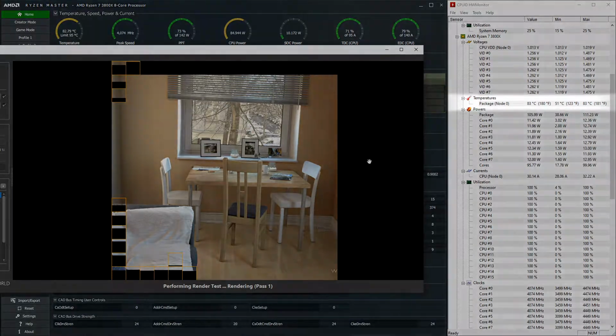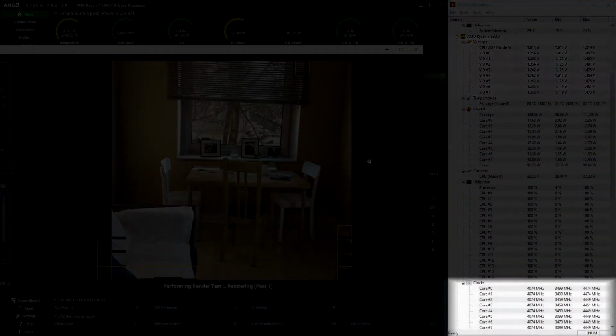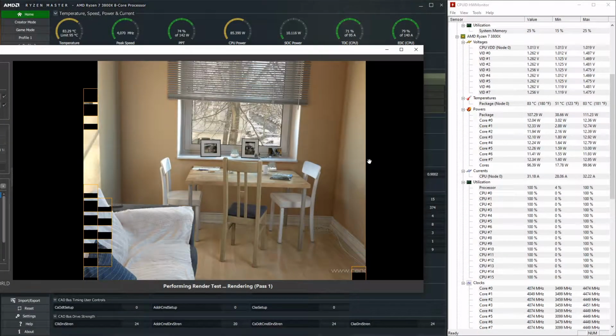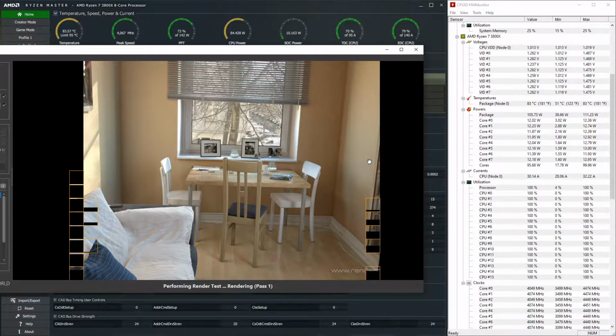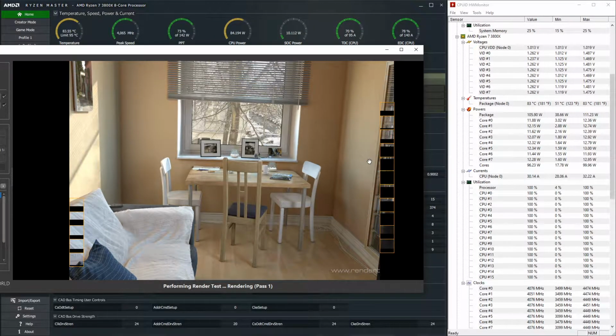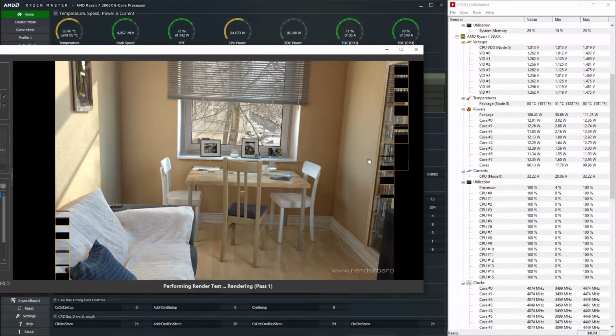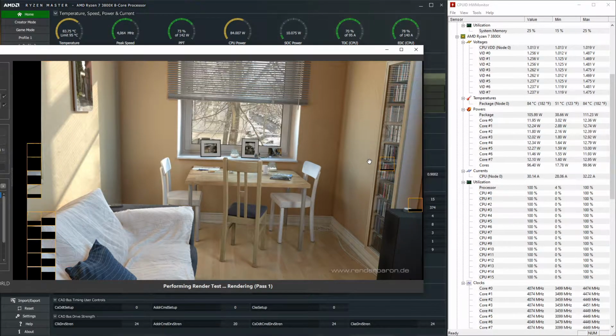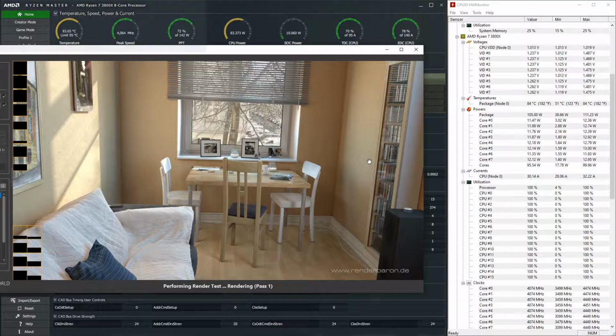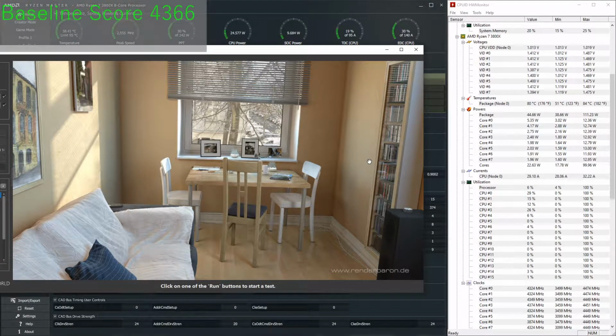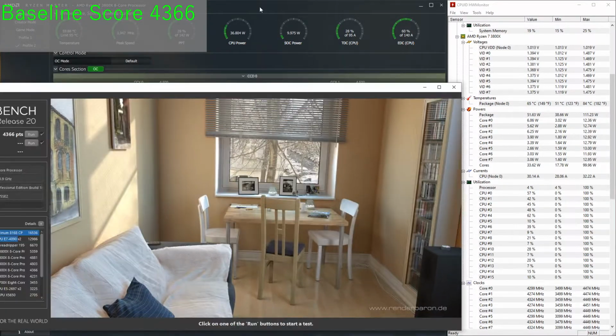At this point, make sure to check your temps, voltages and clock speeds under load to know where the trip is headed. Under these conditions, my chip peaks at 85 degrees Celsius, feeding 1.23 to 1.25 volts, while after the boost is over, it stabilizes at 4.05 GHz.